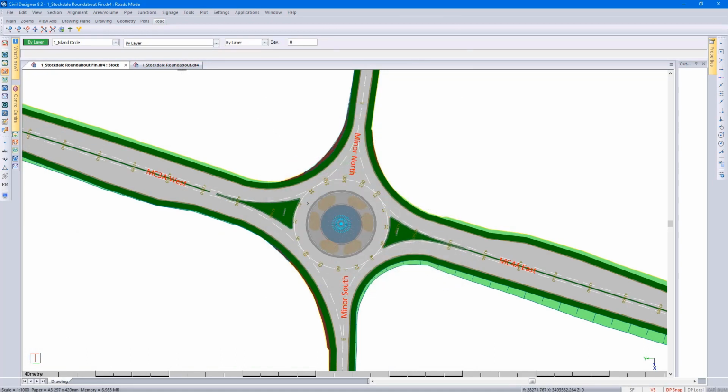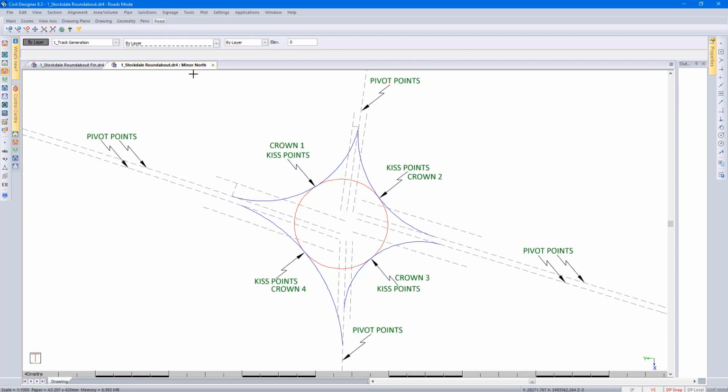Going back to the original project, I've selected this particular project because, as you can see, the four roads aren't straight. And at the same time, if you look at West and East Road, their road widths are very different to the North and the South roads. Now, because of this, you've got to be careful when you put in your road edges. Let's look at that in more detail.